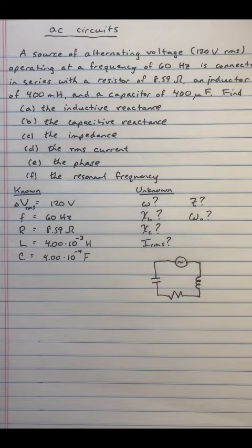It means basically that there's something very akin to resistance. Now, it's not officially resistance, because, at least for an ideal inductor, there's no heat loss due to resistance. We're just simply talking about a natural reaction that the coil has because you're changing the magnetic flux through it.